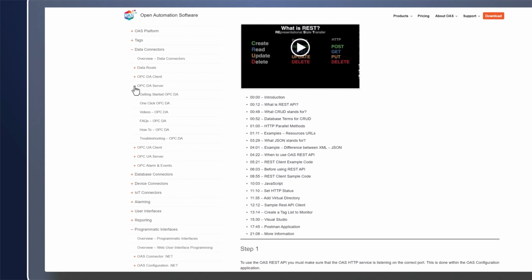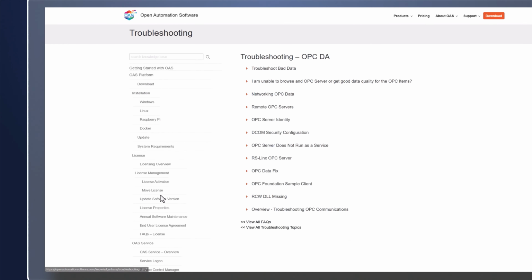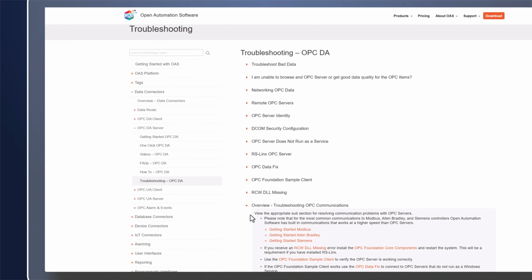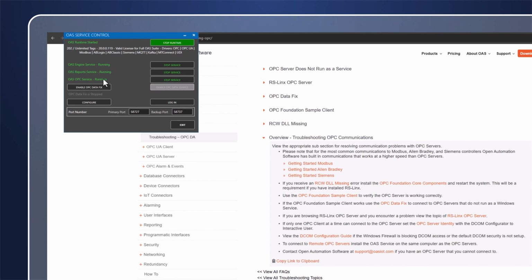If you have more questions about connecting to OPC DA servers, be sure to check out our Getting Started page and the knowledge base article on the one-click OPC DA feature we just demonstrated. Also, some of the commonly asked questions about OPC DA, and then also a troubleshooting guide. If the OPC server is not running as a Windows service, you'll see some guides in here on how to use the OPC Foundation sample client to test that OPC server. And then optionally use the OPC data fix, which is very easy to use if you want to run the OAS OPC service as a Windows desktop account instead of running as a service under the system account.